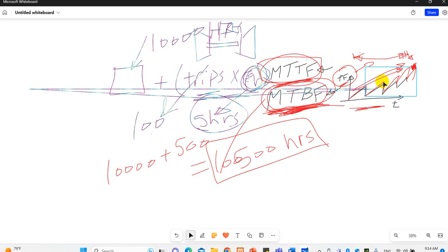Why? Because you replace the defective parts, or you replace the exhausted parts, like blades, bearings, pads, whatever you are replacing. You are measuring the clearances, adjusting RTDs, connections, thermocouples, proximity probes, all this kind of activity to make sure that the equipment is running reliably. Then once again you start running the machine, and the probability of failure increases by time until you reach the overhaul running hours.